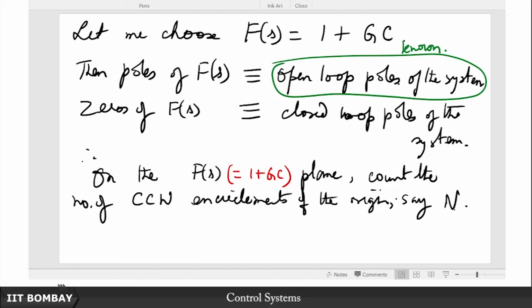How to count this? Well, the plotting is the difficult part. Once you have plotted it, you just take the test radius or the test phasor. Don't try to think of ways of winding around and finding an escape route, because that's cumbersome. Think of this test phasor that you draw from this origin, and see the net number of times this goes through. That will tell you everything that you need to know.